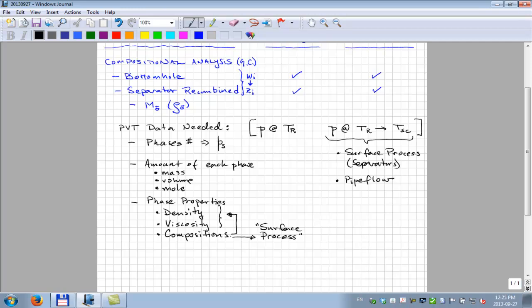So we actually have another dimension in this PVT space, which is composition. I'll just write it up here for various compositions. So we call this a pressure temperature X for composition, or Z space. And so we might collect 3 samples, 1 in the gas cap, 2 in the oil, and if we do the PVT analysis that gives us pressure temperature dependence for each of those 3 samples, in effect what we've done is that we've calculated a large pressure temperature composition space with measurements.